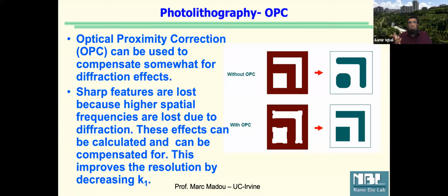The upper figure shows that if there is a very small feature, like an L-shaped thing or a square, because of diffraction limitations, when the light projects, the edges don't come out sharp. So there have been some physical interventions. If you look at the mask design in the lower picture, you see they have added some extra increased edges, like here, or here.